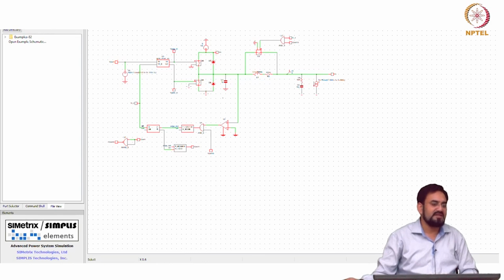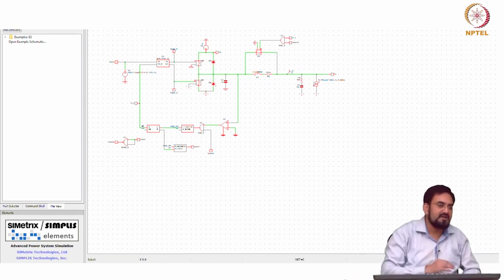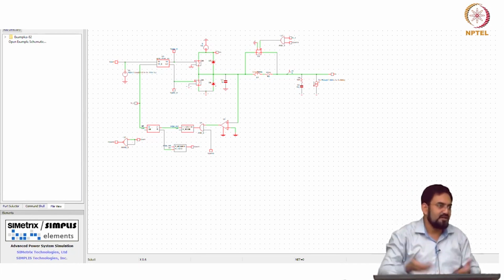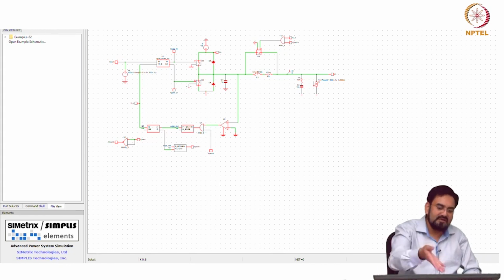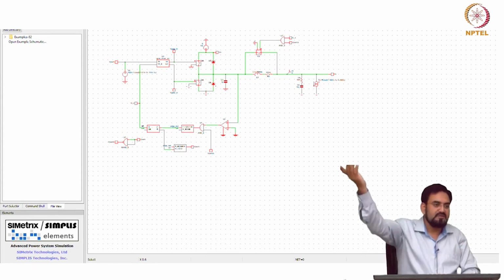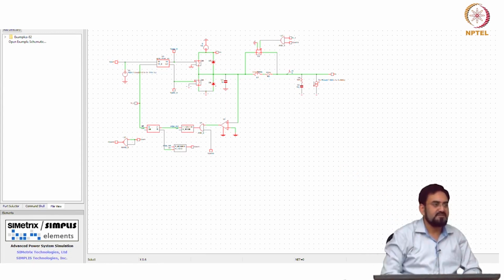So, they will limit the voltage, otherwise it can go anywhere. If these body diodes are not there, then it will kill your circuit actually. This is a high Z and it may go anywhere actually, 100 volts, kilovolts, you do not know. So, these diodes will protect that node itself, they will clamp it to between minus 0.7 and VDD plus 0.7.